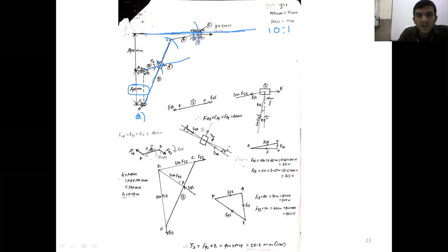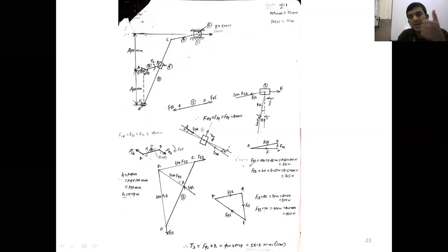Now once you get point D, in the freehand sketch you draw a slider and the cylinder on a horizontal surface, right? And then at point B also, in the freehand sketch, draw one more slider here. Okay, this is how you draw the space diagram by taking a suitable scale. First step, identify the type of mechanism. Second step, draw a space diagram by taking a suitable scale.